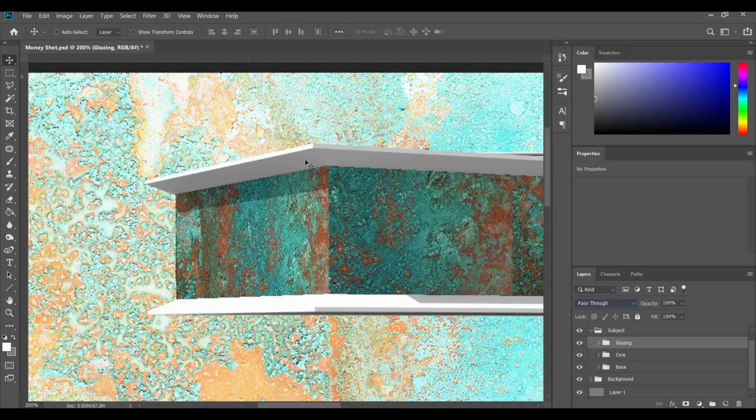So next we're gonna tackle these edges here, these slabs. And if you are wondering why this slab looks like this, it's a design element, but it's also functional. The reason is when it rains, the water will fall down, and you would think that it would hit the glass and the glass will get dirty, but when you do a detail like this, you want to have something called the drip edge, and it would be just a line, a score that goes on the concrete or whatever this is, metal, whatever it's going to be. And when the water hits that line, it accumulates there and then it drips down, and then it falls on this slab here and it continues to run off. It's a way of trying to mitigate water collection on this slab down here.